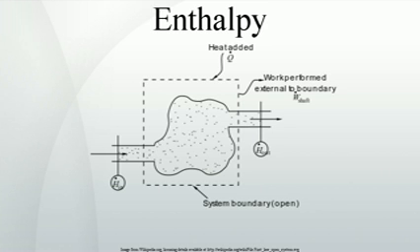Note that the previous expression holds true only if the kinetic energy flow rate is conserved between system inlet and outlet. Otherwise, it has to be included in the enthalpy balance. During steady-state operation of a device, see turbine, pump, and engine, the average dU/dt may be set equal to 0. This yields a useful expression for the average power generation for these devices in the absence of chemical reactions, where the angle brackets denote time averages.